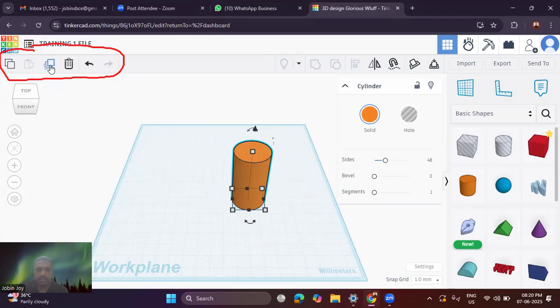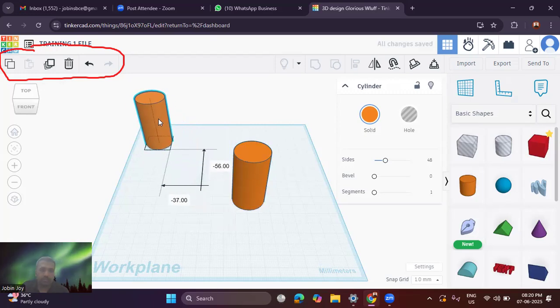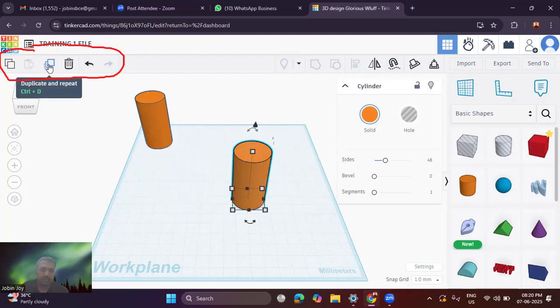So I'm selecting this duplicate and repeat. I'm clicking once. So now a copy is created. Just click here and you can move it so that you can see a copy is created. Again, if you want say 5 copies, click 5 times, 1, 2, 3, 4, 5. When I click 5 times, the copies are created, but they are inside this cylinder.